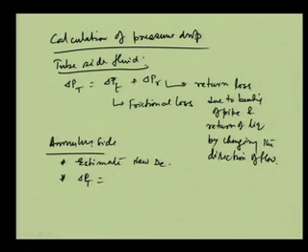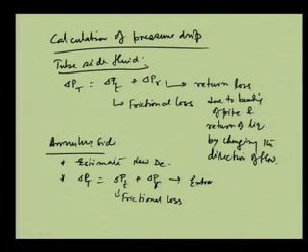And then delta P total in this case also will be delta P T plus, here also we can say, delta P R. So, here this is again the frictional loss, and R is also a loss, usually the entrance and exit losses. The reason is, in case of a double pipe heat exchanger, the material comes from one side and then goes out, so that will be entrance and exit losses.